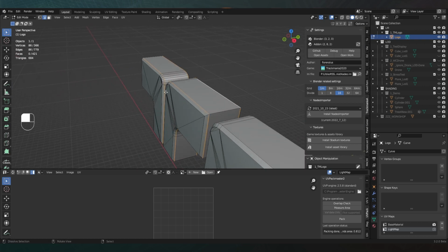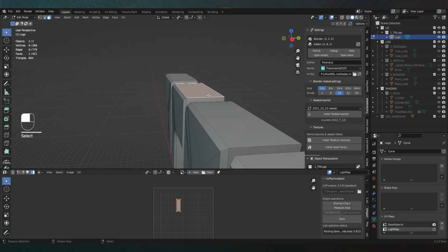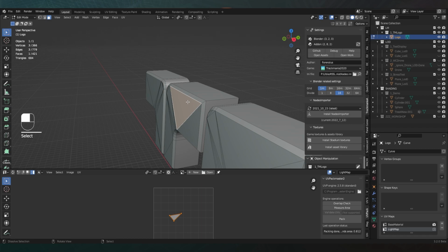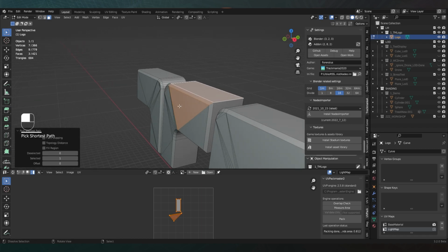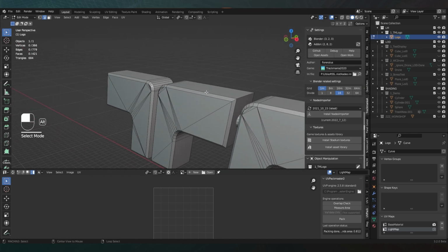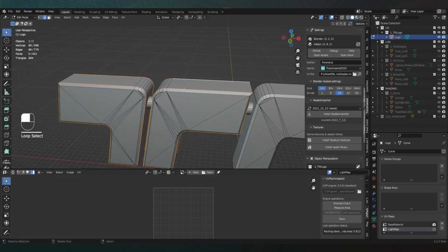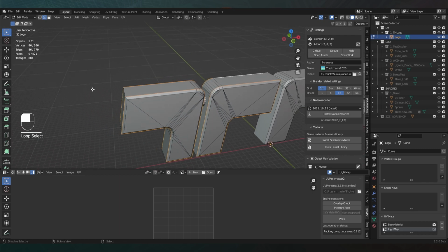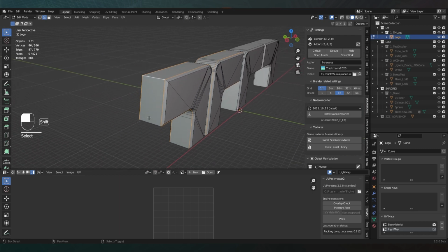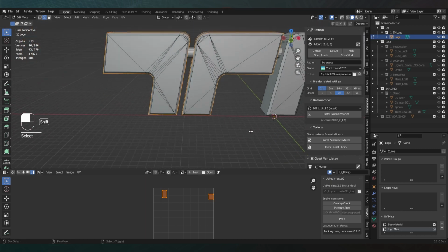This face will receive different light than this face, and when they are one UV shell, it will look pretty strange and not realistic. So what I'm doing, at least for this model, is selecting these edge loops that will be cut. You can see my keystrokes, as I said. We will just select all the edges that make sense to be disconnected from the rest.